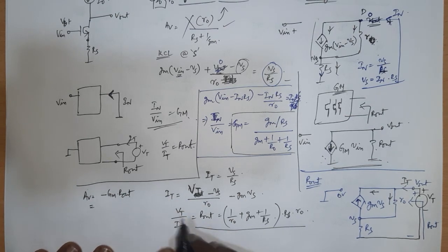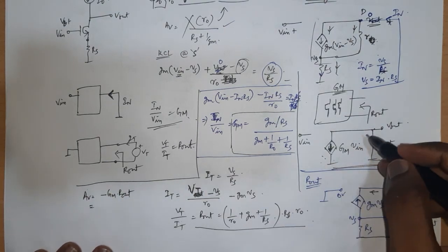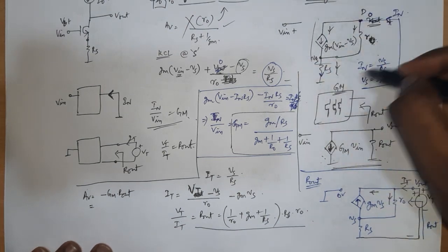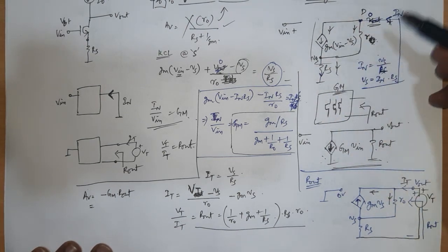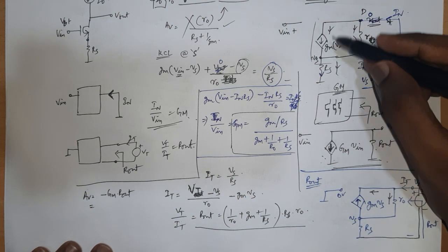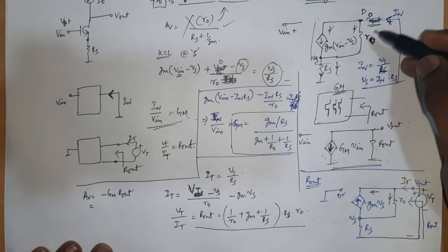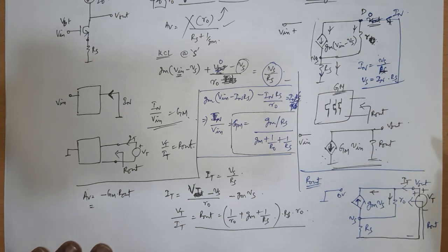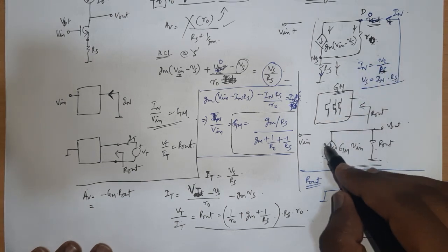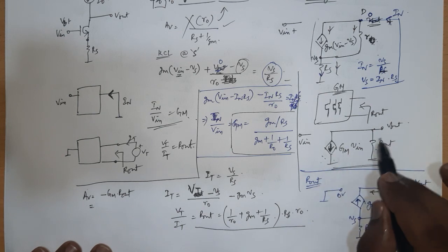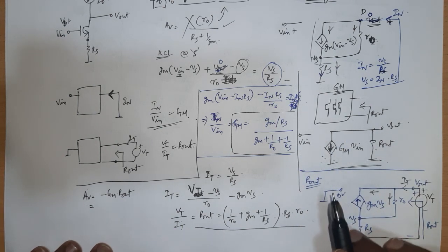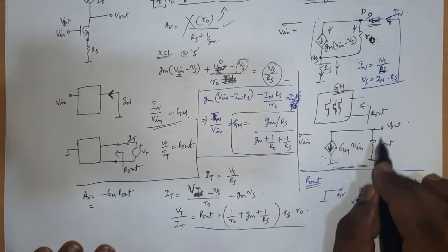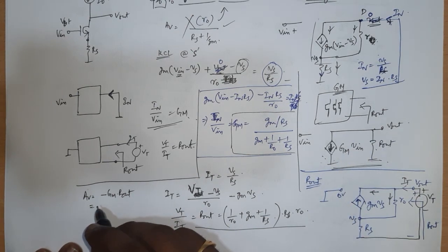See this idea of converting to an equivalent network: here it has only one transistor, but in a complicated situation. If there are a number of transistors, then also you can use this method to represent a single Gm and a single R out for all the transistors. Which will be very, very useful. Even for op amps we can do this. That is what we have done.